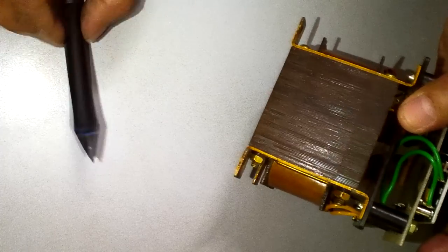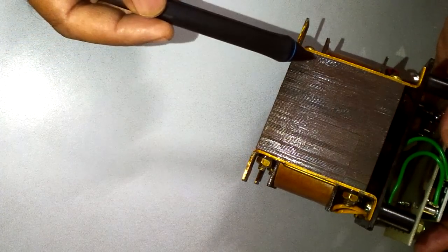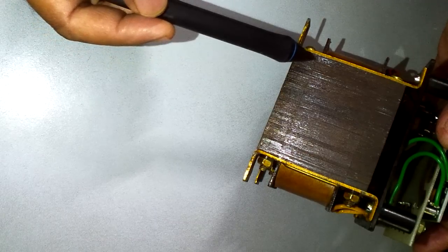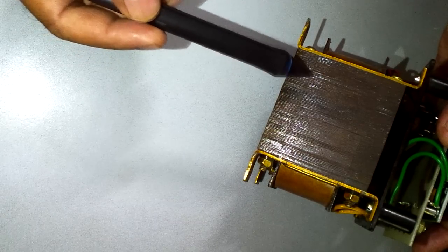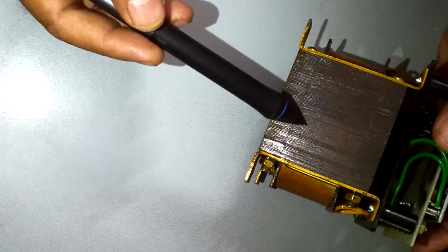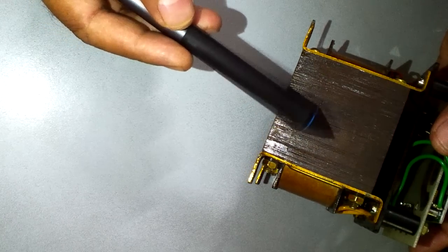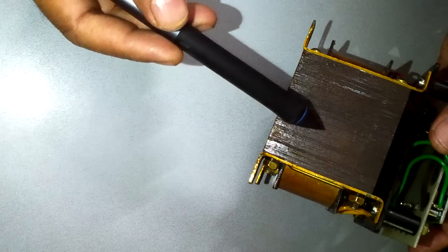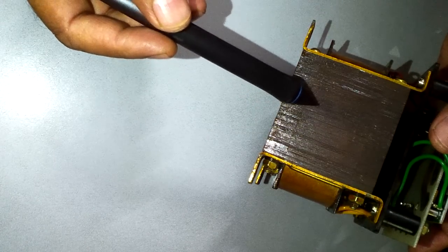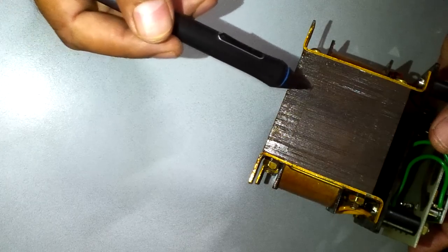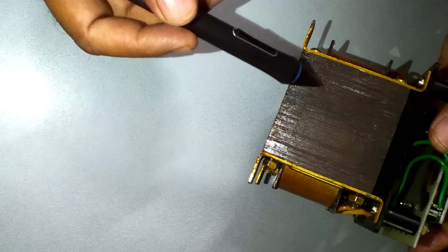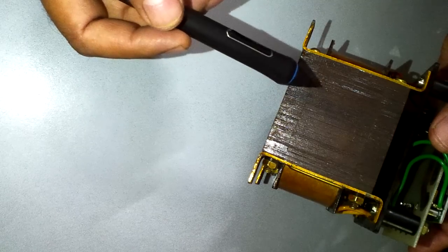I have here a transformer with me. This is a low frequency transformer, and you see here that it is composed of stacked laminations. These are thin laminations stacked together, and then varnish is applied to keep the air pockets out. And these laminations are made of steel. In fact, they are made of silicon steel, and they are called cold rolled silicon steel, and they have maximum flux density capability of around 1.2 Tesla.